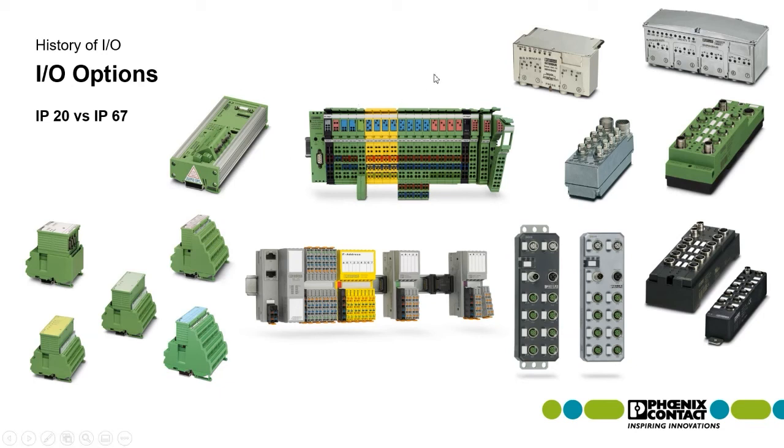So either we're going to go with an IP20 option, which you see on the left-hand side. These are products you would put inside of either a large cabinet or a small cabinet or junction box, we would call it, to collect IO signals and bring them back. Or you take the big leap and say, why do I have a cabinet? Why don't I buy an IO module that is my cabinet? I can just wire all of my IO signals through standard M12 cable sensor connections and put my network interface right on the box. It's almost going to the level of removing the box into the IP67 realm.